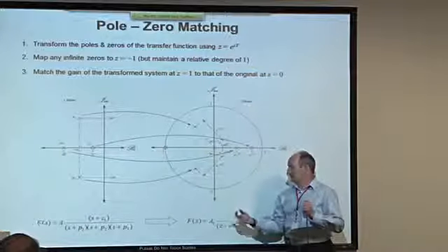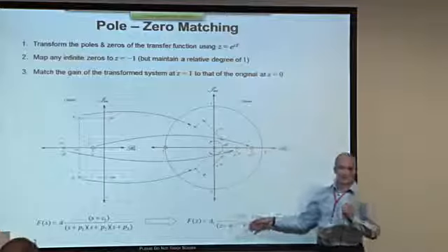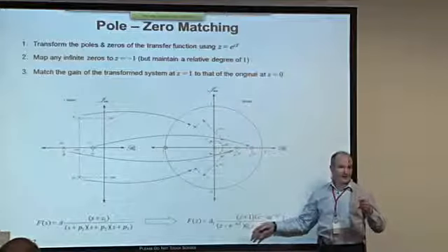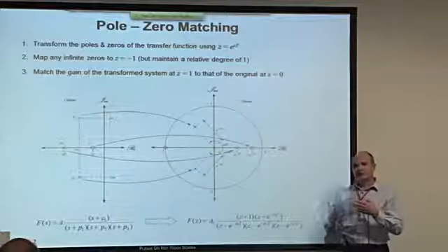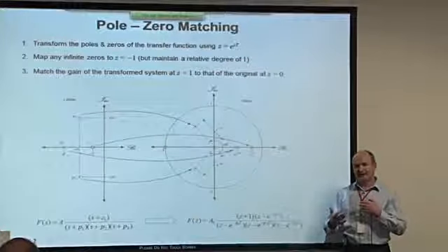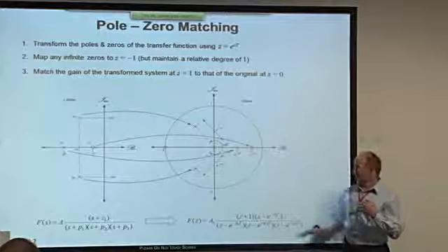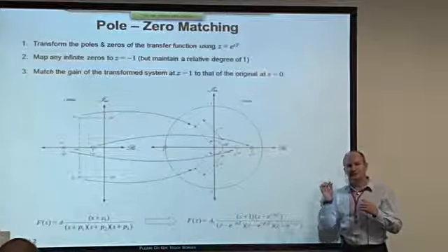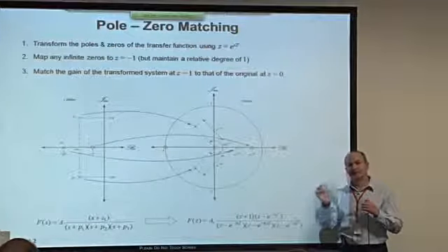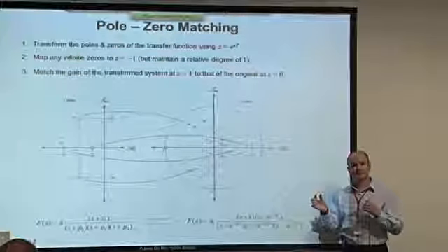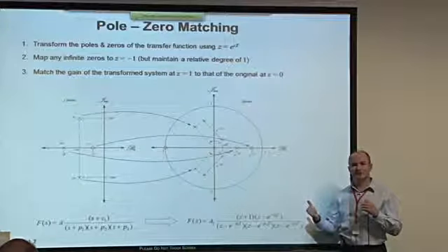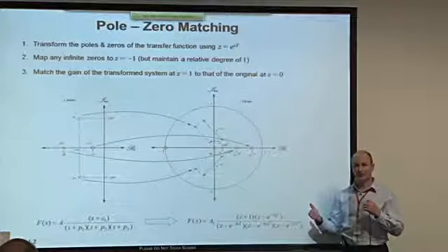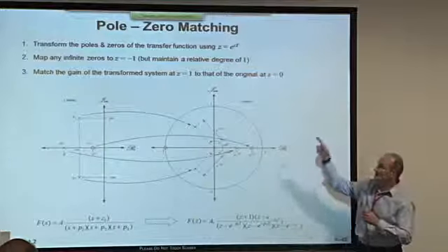Now that's fine because it gives us a whole sample period to compute the control law, but maybe the controller that we've got is fast enough that we can do better than that, significantly better. And if it is, you can get rid of more or less all that phase lag just by computing the output in the same sample period as the new input comes in. All of that phase lag is pretty much due to time delay, the one sample period delay from step 2.